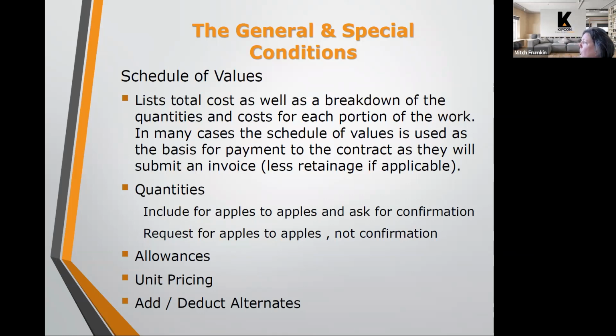When we review bids, we've done enough projects that we can get an idea of what might fall in as an extra in the project. It may or may not happen that way, but just for example, a roadway project typically includes, in addition to the base cost, which, as you may recall, I mentioned is everything that needs to get done on that project, a 15% to 20% contingency for items beyond that base bid that may need to be done, that are unforeseen conditions.